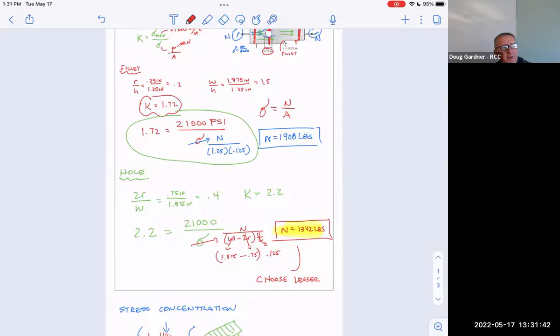Incidentally, have you noticed anytime people pour concrete, it's never just a giant flat slab? The sidewalk right out here, they've got lines cut in it every foot, 2 feet, just lines everywhere cut through it. The rule of thumb in concrete is don't go more than 10 feet without putting a line in the concrete. Now, why do you do that? You're basically taking concrete that used to be 3 inches and saying, right here, it's going to be 2.5 inches. Well, when the ground moves and cracks, where do you think it's going to crack? In that weakest spot, because that's exactly what we just drew.